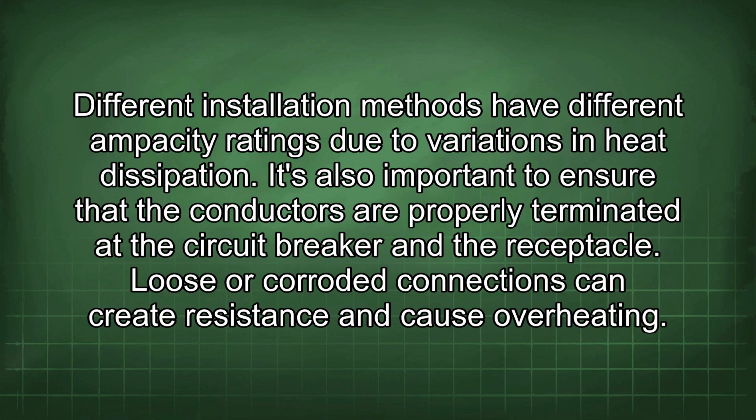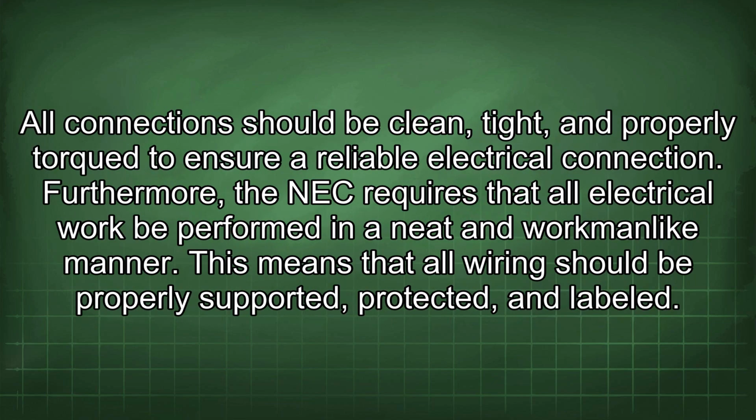It's also important to ensure that the conductors are properly terminated at the circuit breaker and the receptacle. Loose or corroded connections can create resistance and cause overheating. All connections should be cleaned, tightened, and properly torqued to ensure a reliable electrical connection.